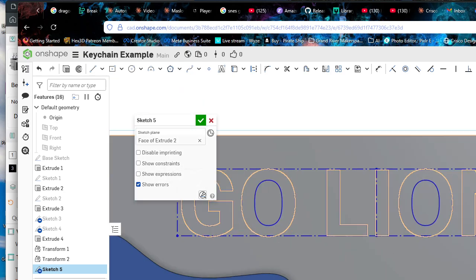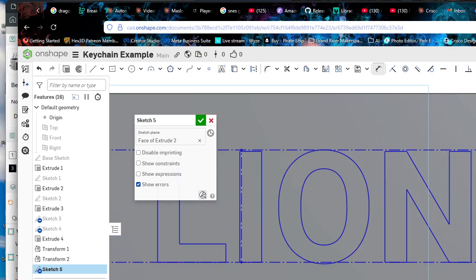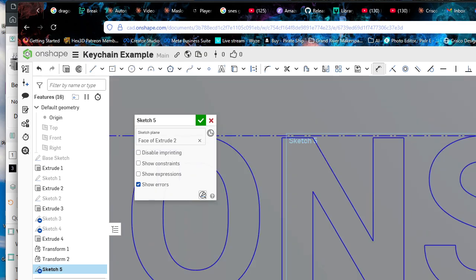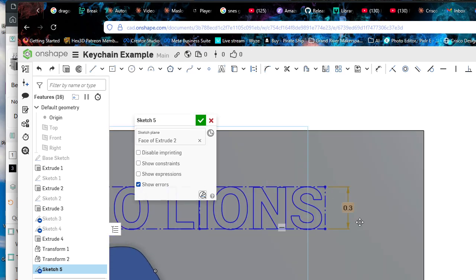Then it's already dimensioned, so you just have to basically type in a number. So if that is too big at that size, go smaller. Okay. So what he did is he was trying to dimension this line. He clicked on the line, but didn't see a dimension. You always have to move your mouse to the left or the right in order to see the dimension. That's another common thing that happens. Whoa, it got real small.